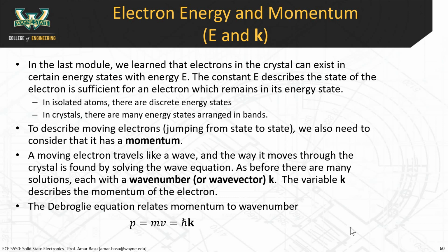So in this chapter so far, we've talked about what is doping, okay? There's N-type and P-type dopants. We looked at what the energy band diagrams look like when you dope a semiconductor. Then we started looking at mechanisms of how they move. We talked about drift current and how these carriers can move in response to a voltage, and as they move, they bump into things, and those collisions, referred to as scattering, slow down the electron. And because of that, there's something called electrical resistance that develops. We connected the concepts of scattering with electrical resistance.